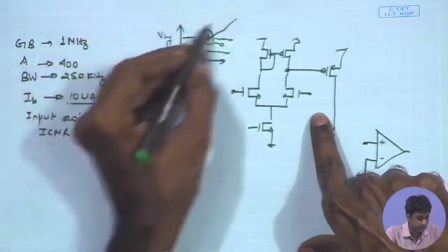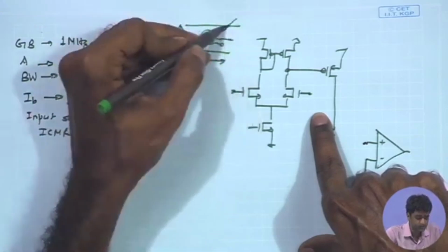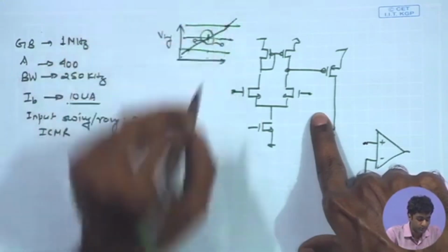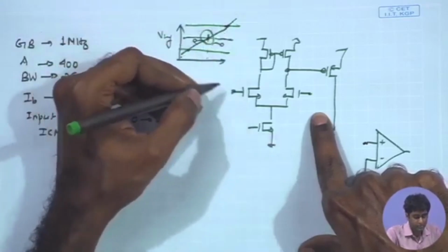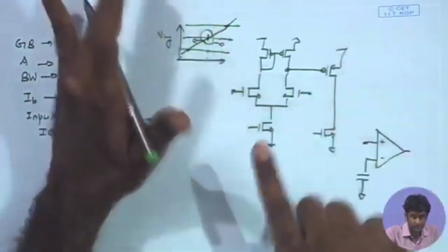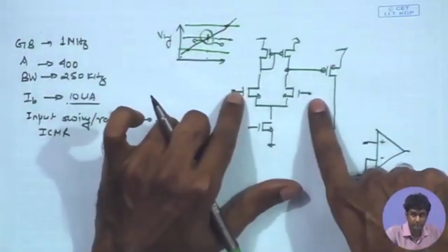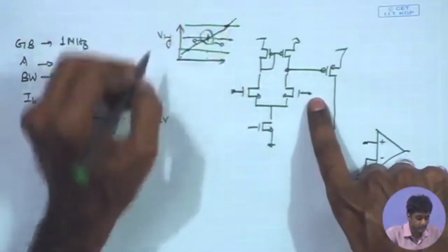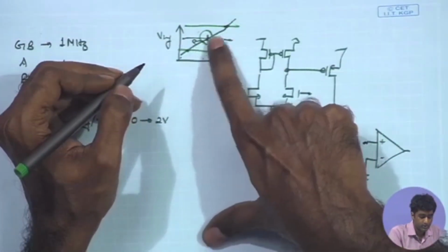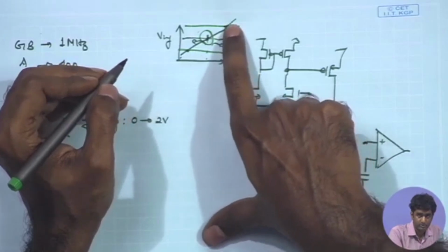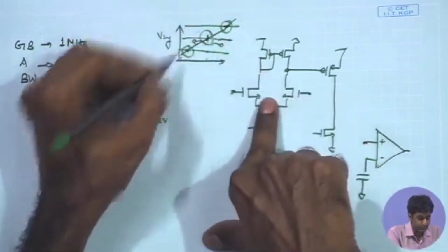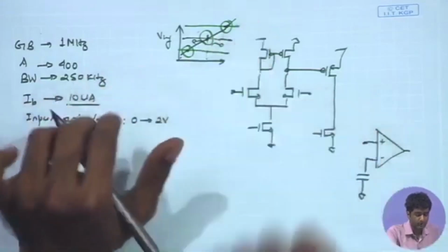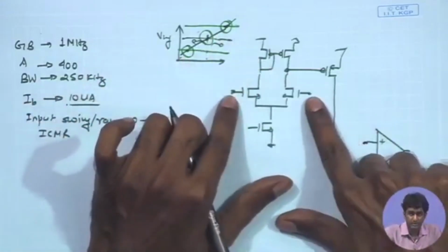Likewise, on the other hand, if the sampled voltage is constant and it is pretty large, we would also expect that the comparator should also work fine. The transition of the comparator should be fast enough even when your ramp is approaching the sample voltage, which is high. So, irrespective of the sample input voltage, at all these points the comparator should be well behaved,